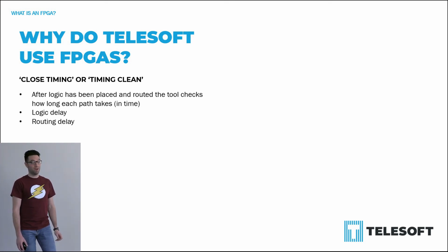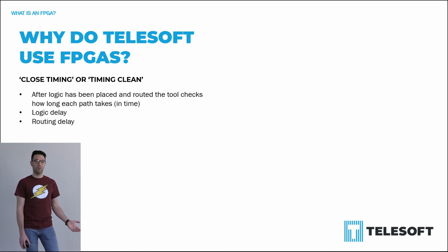So this massively parallel processing gives huge acceleration. It doesn't matter if you're accelerating maths functions, if you're doing fingerprint hashes, anything like that. Anything that a processor can do, an FPGA can also do really quite quickly, particularly if it's an iterative process. Things like hashing algorithms or compression, decompression, encryption, decryption, these things are really well optimized for hardware implementations. Now, counterintuitively, this huge acceleration also gives you a massive power efficiency. So if an FPGA is 1,000 times faster than a processor, and you are running 1,000 processor cores, you're going to use a lot more power than one FPGA. So all of this massively parallel processing gives us acceleration, which also gives us huge power savings.